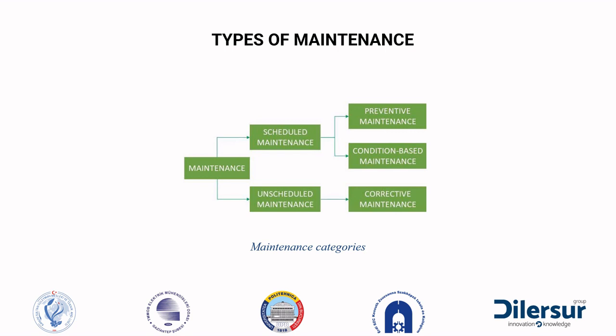1.2.1.1 Preventive maintenance. Preventive maintenance is performed before machine or system failures occur and involves routine inspection, servicing and cleaning of solar panels at a scheduled interval of time. The goal is to minimize downtime and unnecessary production losses, to improve panels' performance, to increase availability and to reduce the probability of equipment failures.